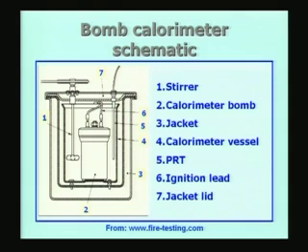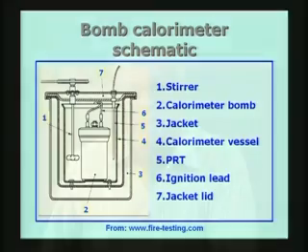The reason why we want to fill the bomb with high pressure oxygen is to see that the combustion reaction is going to take place completely. That means that the entire specimen, the entire mass of the pellet which is taken inside is going to completely burn, and the combustion products are going to be formed from that.